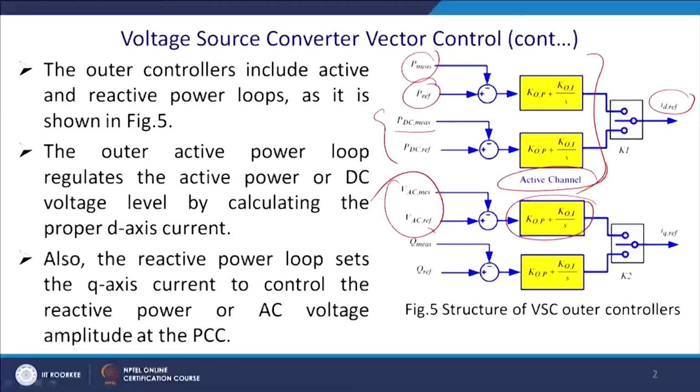Also there may be reverse operation, when converting from DC to AC, where we have a surplus of power, and you have to inject power as given by the grid code. Only when your voltage is healthy can you afford to do that.